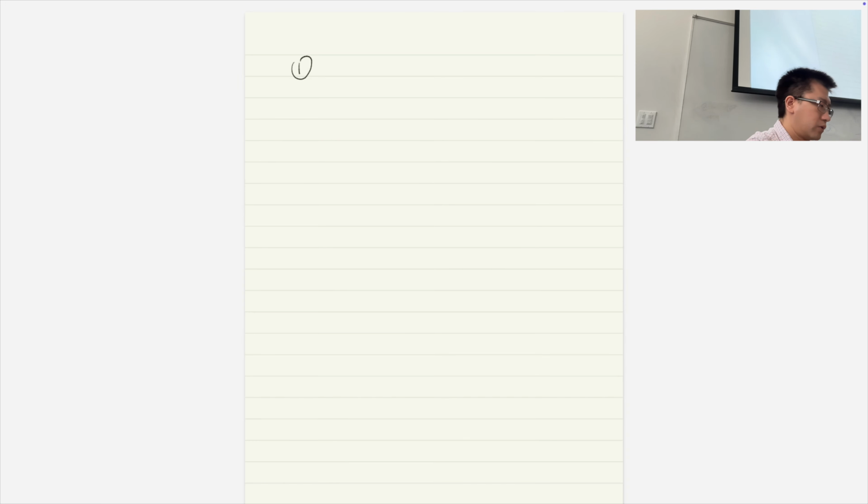Okay, first, let's take a look at how we can solve the capacity of the parallel Gaussian channel problem, right? So here, as we said before, we have a power allocation. So we convert the problem to a power allocation problem. Basically, we want to maximize the summation of the capacity of all the channels.